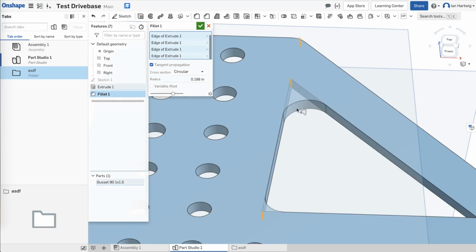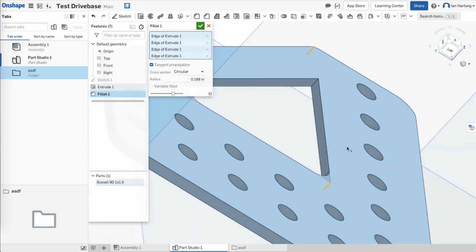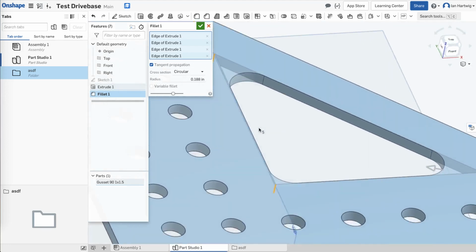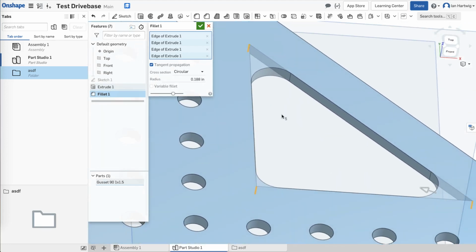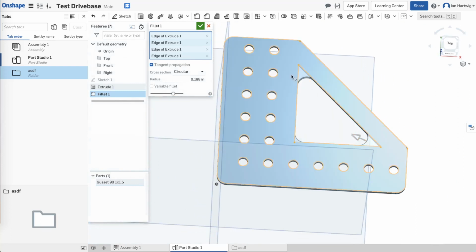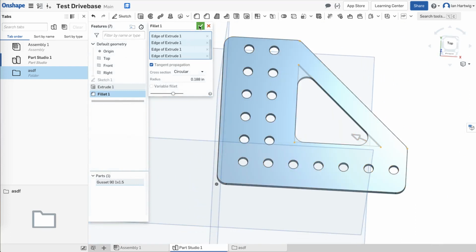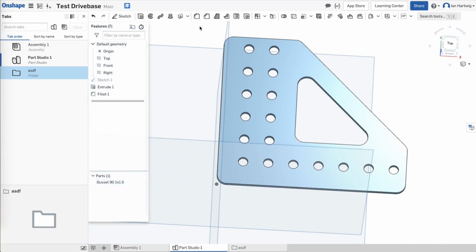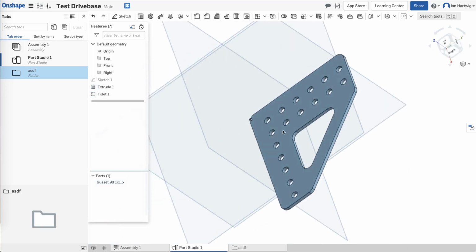So we can add this line and this line, and to select this area again, to orbit, I'm doing a right click and then dragging my left finger on the touchpad or just moving the mouse. Okay, and you can see that it's shaded in as filled into those areas. And we just hit check mark to accept. And now our part has been modified in 3D.